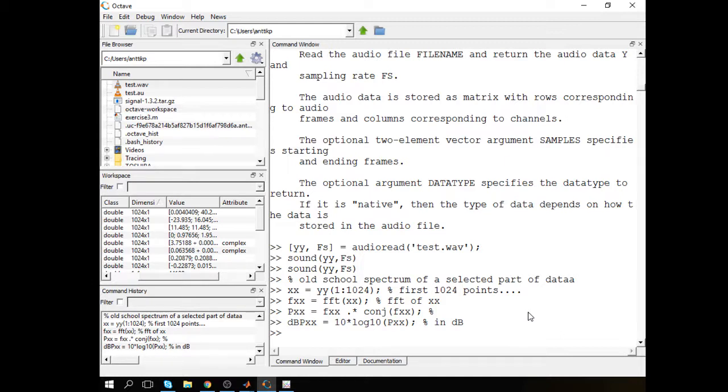Now the corresponding frequencies. Okay, what did I say about the frequency scale? So now basically we have divided that 1024 data points into exactly 1024 data points in the frequency axis, where the 1024th point would actually be the sample rate. So that's your scaling right there.